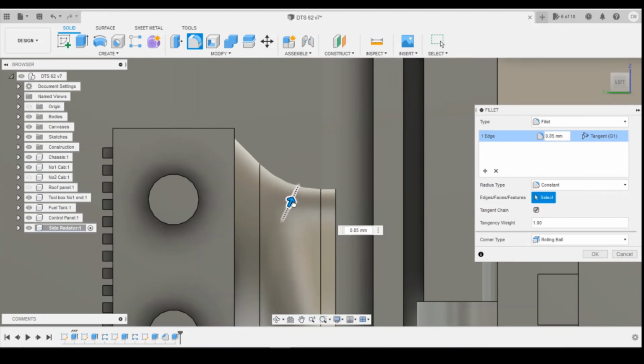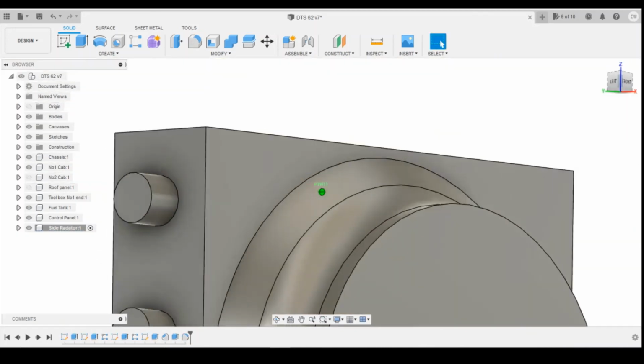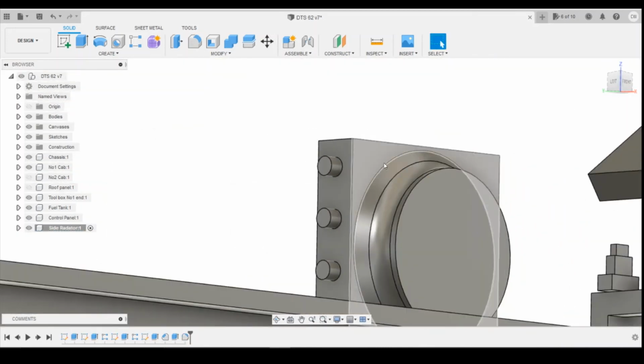So if we do the chamfer, extrude the profile that's left and then fillet that curve so you get that curved shape coming around here. So I'm going to curve that to 0.75. Yeah, I think probably about 0.75 looks like the best. I'm going to go with that. As you can see, I get that curved shape all the way down then.